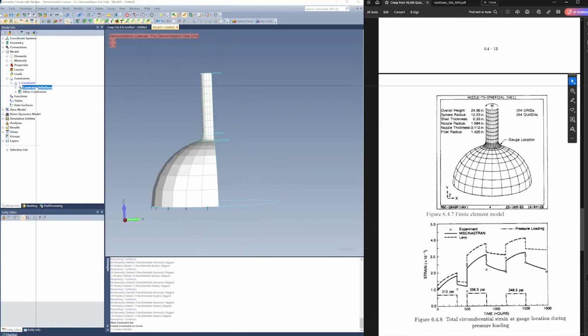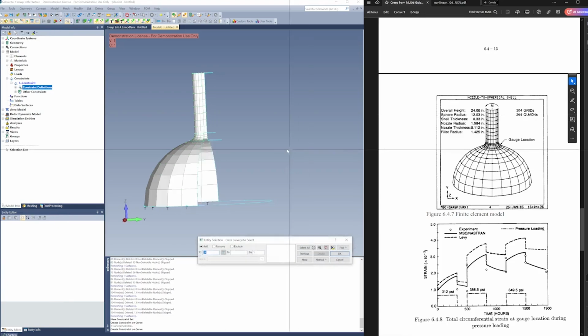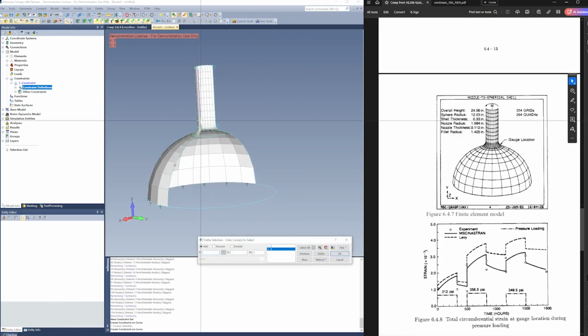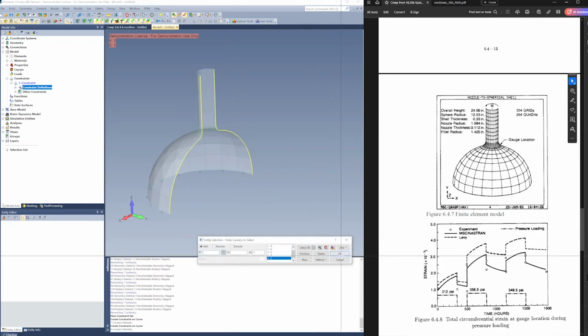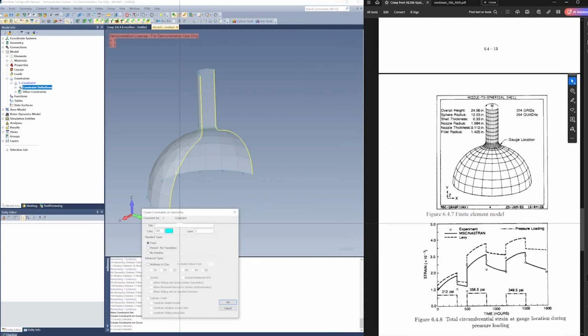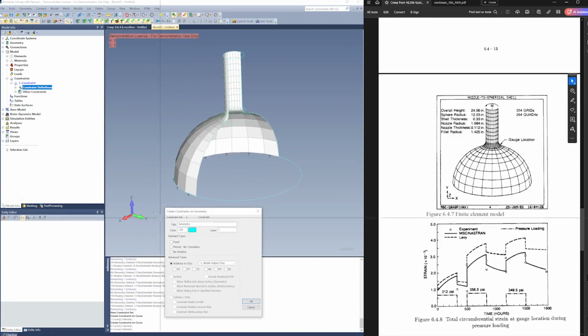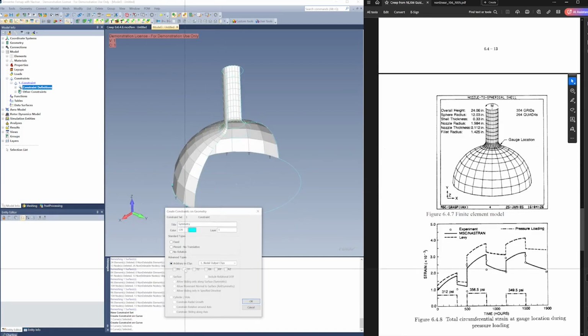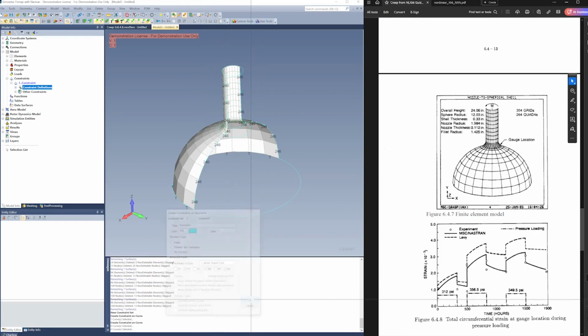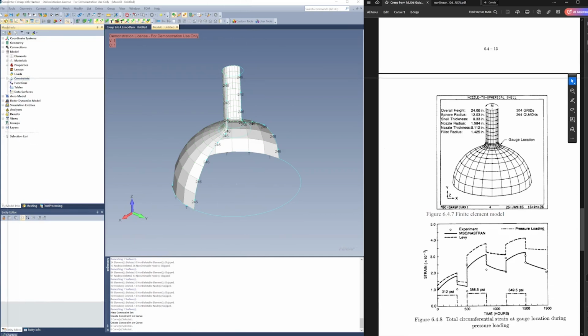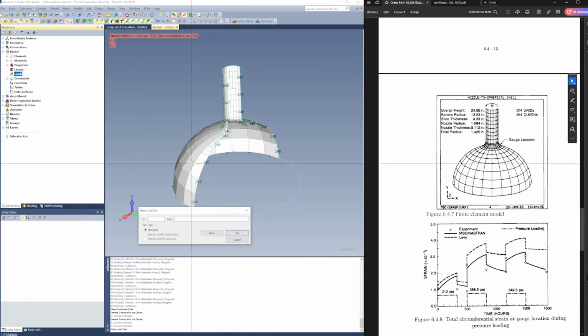And then we'll do the symmetry here. Do a highlight. Okay, that looks right. Call this symmetry. There's no direct shortcut for symmetry on this curve, but this is TY. You can see from here, that's in the TY direction. So it's always TY, and then the other two rotational degrees of freedom. So now we've got our constraints. Let's go ahead and define our loads.